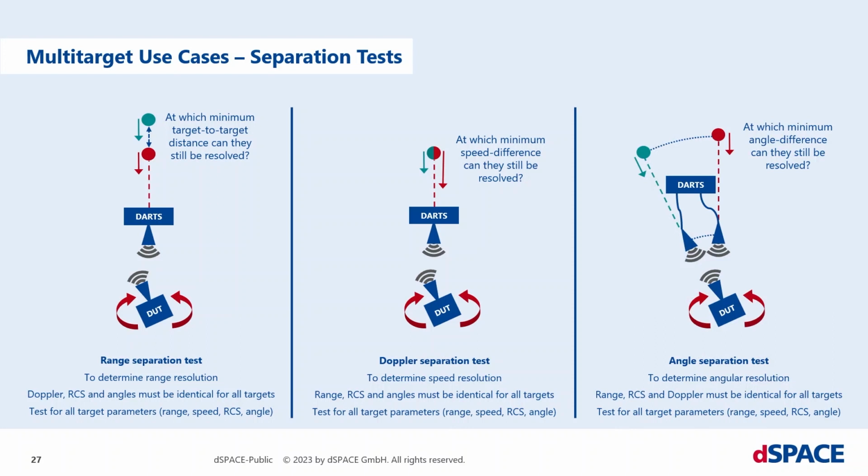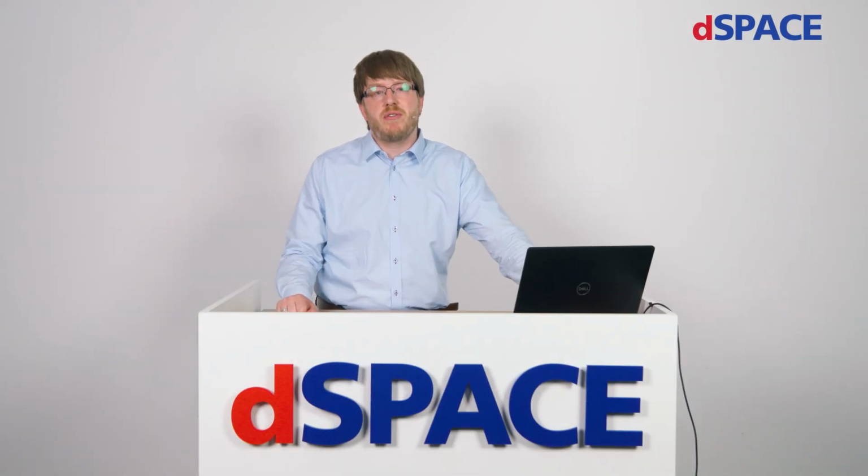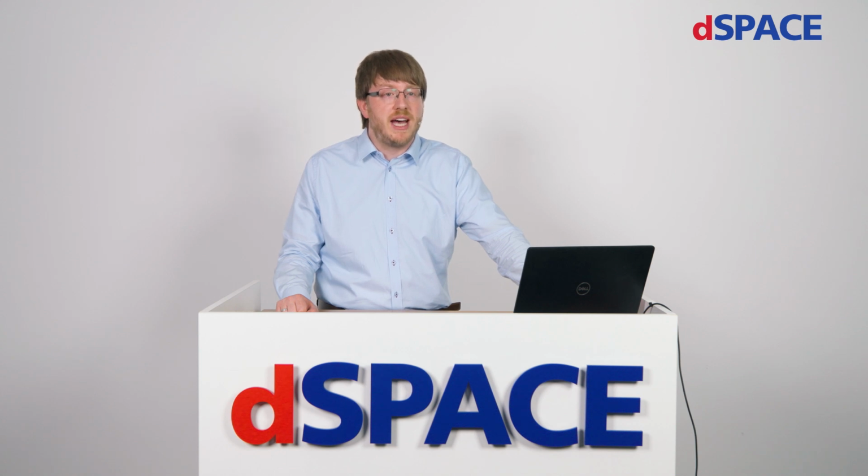And at last, there is the angle separation test. This test has to be performed both for azimuth angle and for the elevation angle resolution. These are typically very different for automotive radars that have a much higher resolution in the azimuth angle. In some cases, only the newest generation of radar sensors start to measure the elevation angle at all. The relative angle between the targets is not controlled electronically within the DARTS, but by moving the front ends from which the targets are simulated mechanically.